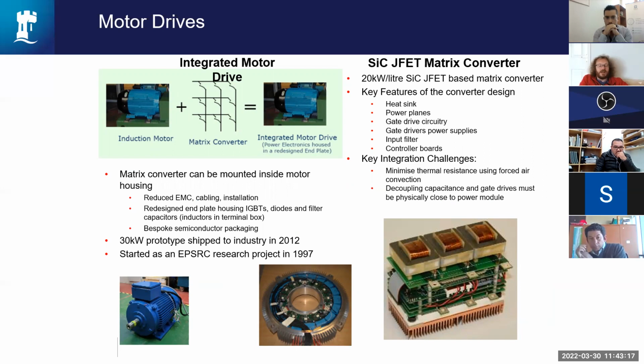How have we done that? Well, we've done that because we understand the power electronics. We've also done that because we understand the thermal management, getting the heat transfer from that power electronics into the air. So what you can't see in that picture is a total redesign of the heat sink to get the heat out into the air and the fan.